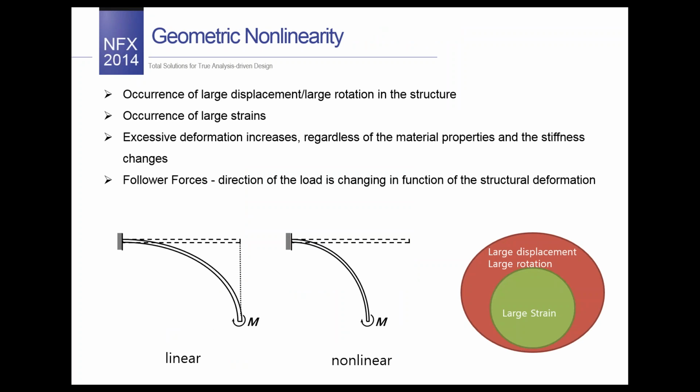Okay, so now let's talk about geometric nonlinearity, and I would like to say a few words which may be related to the following phrases: large strain, large rotation, large deformation. Buckling itself is related to this large rotation and deformation. This geometrical nonlinear behavior occurs when the changes in the geometry of the structure due to its displacement under load are taken into account in analyzing its behavior.